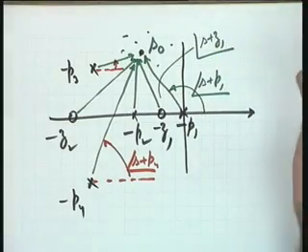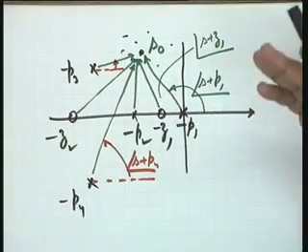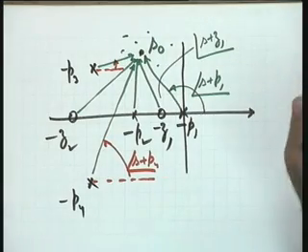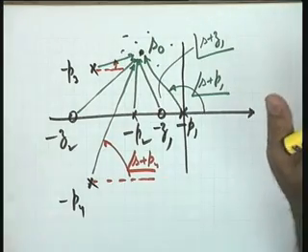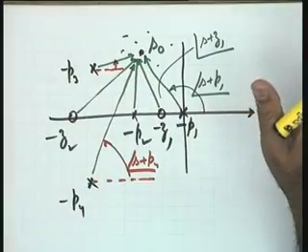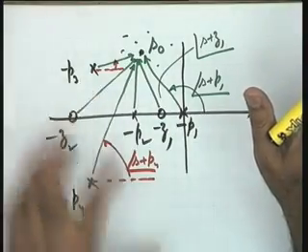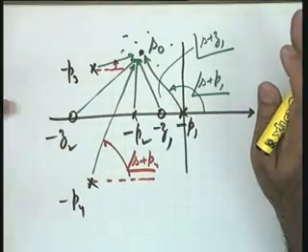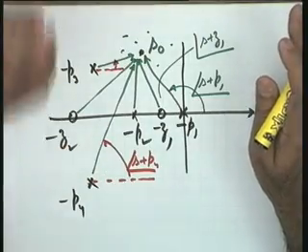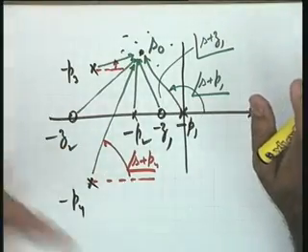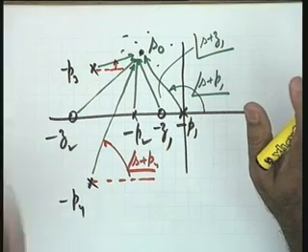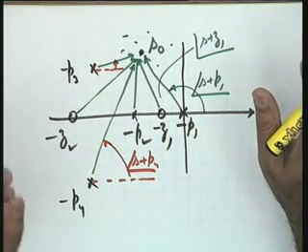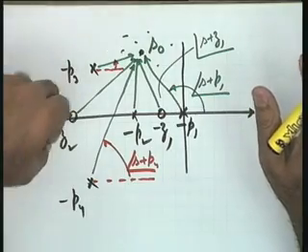This is the computer aided graphing, and all the computer aided design tools are equipped with computer aided graphing of the root locus today. But fortunately, there are some guidelines which quickly give you an idea as to what should be the points in the entire S plane which should be tried for the angle criterion. Which should be tried, I say. It does not mean that the guideline will give you the root locus plot straight away, but the guideline will take you very quickly close to the actual points.